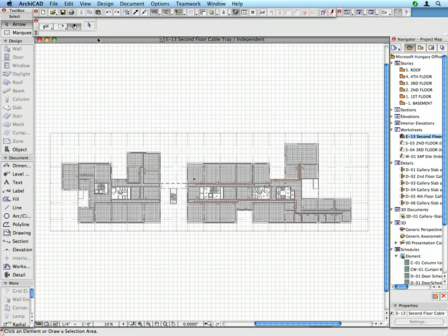Attribute pollution is the unnecessary increase in attributes due to the placed and xrefed DXF DWG files. When we place a DWG file as a drawing, we do not get many unwanted layers and other attributes. When exploding a drawing, all elements of the DWG file can be transferred to a single layer, as you were able to see in the previous steps.